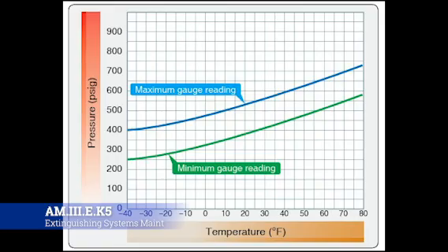Now, the maintenance manual will have all of this in there. In terms of the task, it's very simple: look at the bottle. Is it in the green arc? If it is, it's good. If it's not, then it's bad. Barring random conditions, which will also be laid out in the maintenance manual. So really, if you just follow the maintenance manual, you'll be just fine.